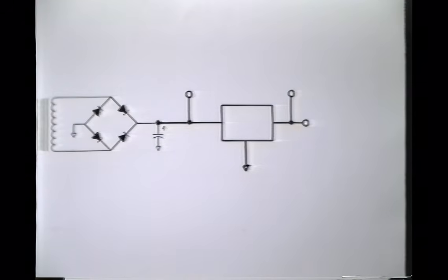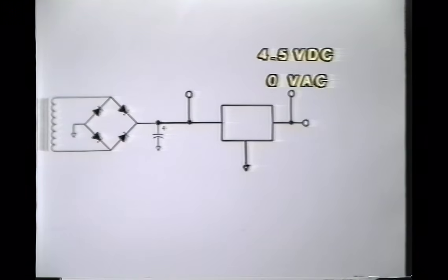If the output voltage of the regulator does read too low on DC, but there's no AC when you switch your meter to read AC volts, remember, check the input voltage first before you change the regulator. Remember, garbage in, garbage out. But if we read a good input, in this case 12 volts DC in to a 5-volt regulator, and a low DC output with no ripple, then the regulator itself has to be the cause of the problem.